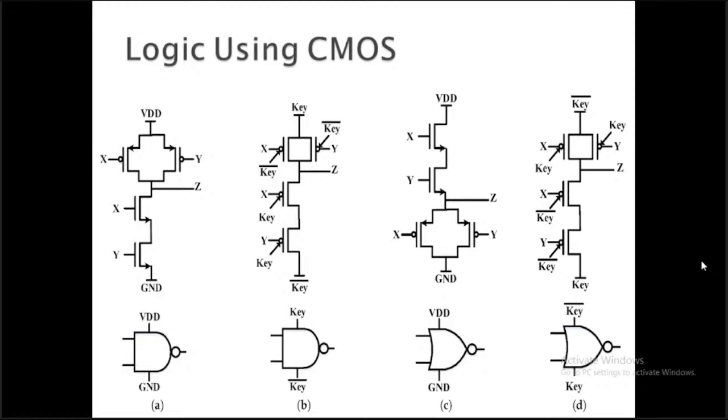Next, logic. We implement those digital gates using the transistor level. You can see here this is the NAND gate. The NAND gate is defined by these transistors, so PMOS and NMOS are connected here. PMOS is usually called a strong one. It is usually used for taking 0 to 1, and NMOS is usually used for discharging the circuit.